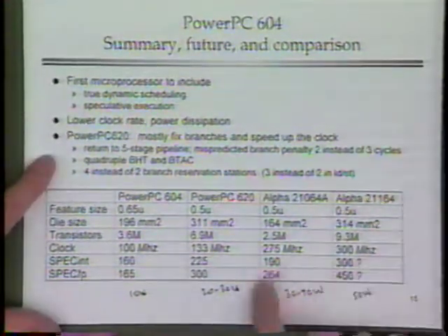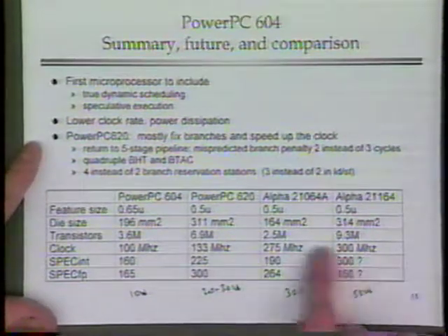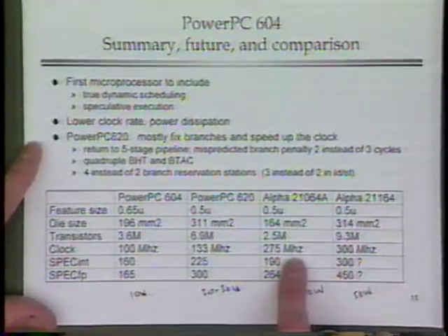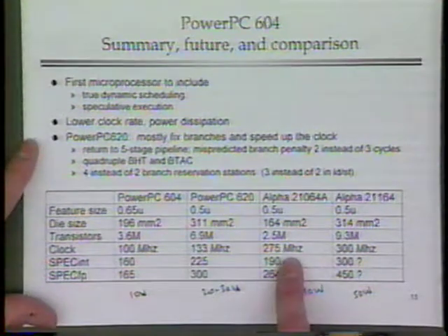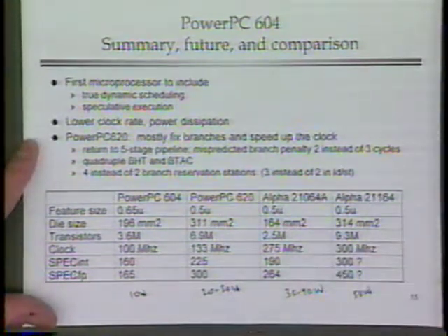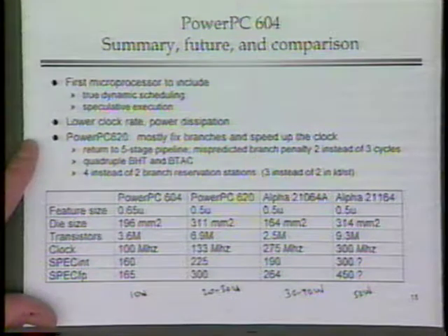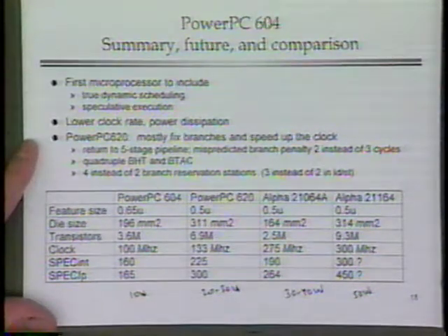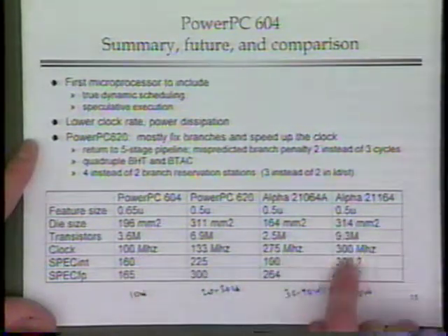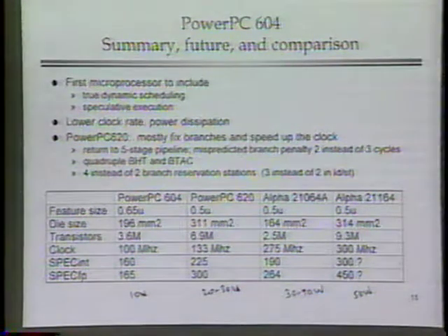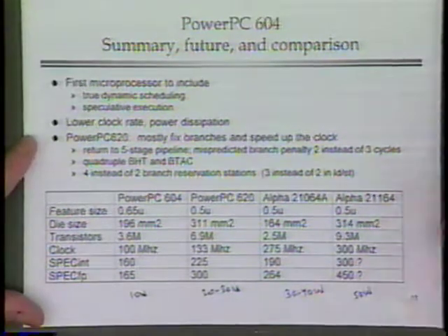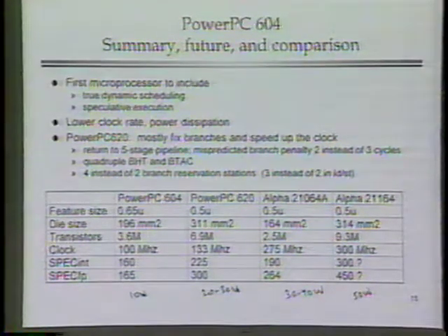So a big difference. And also remember a big difference in the surrounding circuitry, because in order to get memories and caches and clocks and buses and so forth running at 250 to 300 megahertz, it's a different design ballgame. This is not an electrical engineering course, at least not at the circuits level, but going from 100 megahertz to 300 megahertz introduces all kinds of additional radiation problems, transmission line problems, and it changes the qualifications that the designer needs to be able to design a board to work on a chip like that.